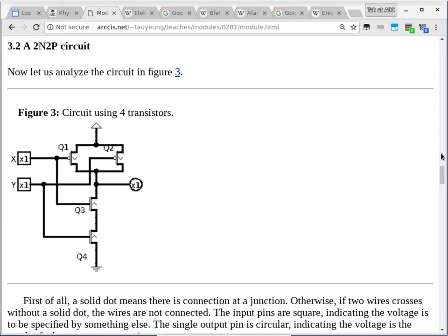because this symbol, the little triangle at the very top part of the circuit, means positive voltage. It's called the supply voltage. And then this little symbol at the very south end of the entire circuit is called the ground symbol. Ground symbol basically means 0 volts. And then the other symbol means some kind of positive voltage. We don't know exactly what the actual voltage is because that depends on what type of transistor we are talking about, but we know it is positive. Are we doing okay so far with this?